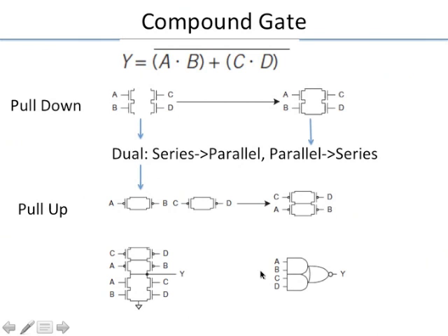Now this is called an AND-OR-invert, 2-2. That means there is an AND gate in the beginning, followed by an OR gate, followed by an invert. So it's an AND-OR-invert. You could implement this gate using these specific ANDs and ORs, but here it's been done in a single stage. It's called a compound gate. This compound gate is much more compact as opposed to a gate like this. We'll see that in a couple of slides, and I'll come back to this.